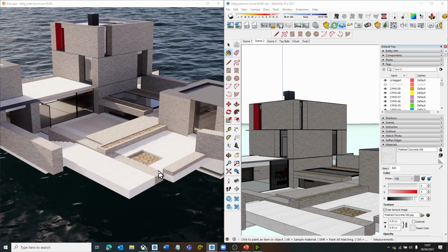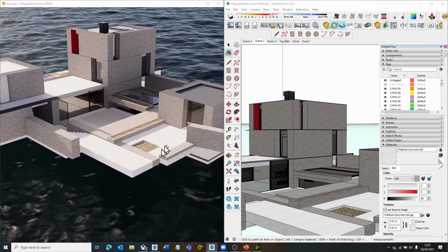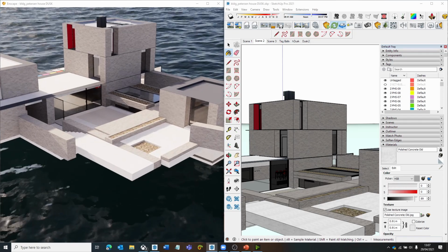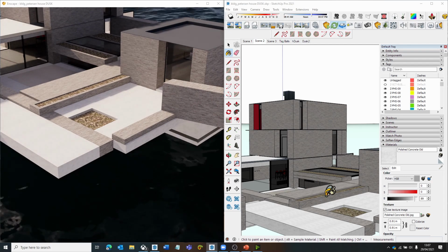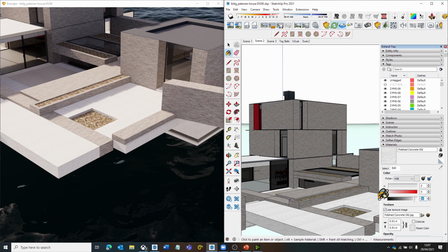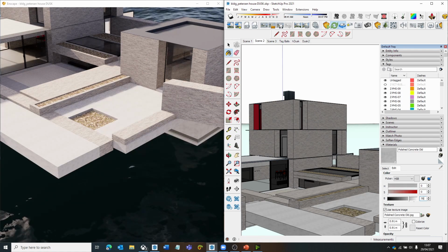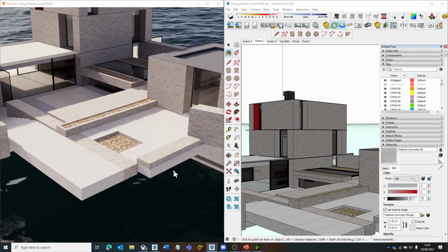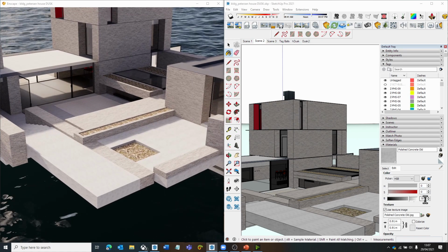And this is reflecting back too much light. I think you probably agree that this is not meant to be a white concrete that looks like snow. It's probably meant to look like a light grey colour. So I'm going to decrease the value of that material to within a more appropriate range. I'm going to take it down to 70, which is less white than paper, but maybe at the brighter end of the scale. I still think that's possibly a little bit lighter than I'd like it to be.